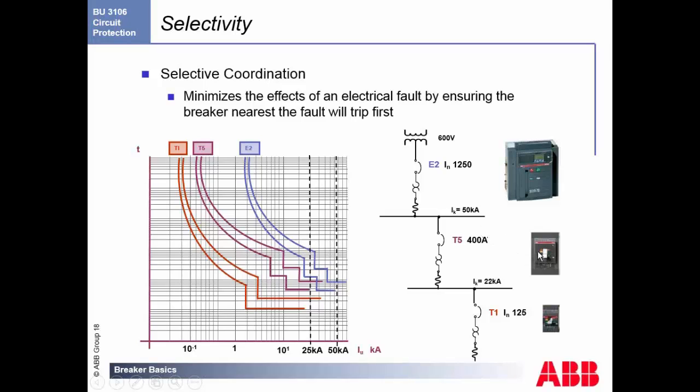So you would choose lower breakers and put them closer to the load so that if one conveyor belt has an issue, only that conveyor belt will pop. As you can see, they're setting the trip currents so that the one closest to the load, closest to the conveyor belt in my example, will be the first one to pop.